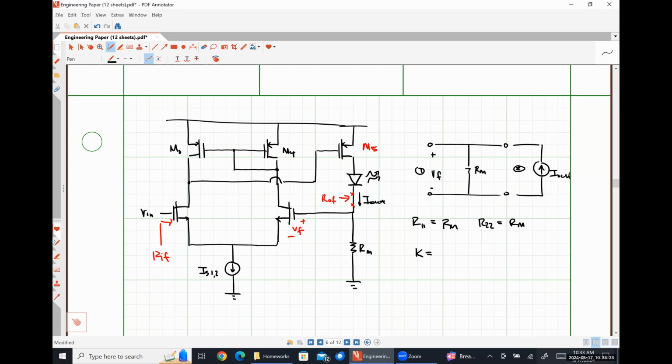It's literally that. If our input signal is a voltage and our output signal is a voltage, it's a feedback voltage amplifier. Input is current, output is current, feedback current. Input is current, output is voltage, feedback transresistance, whatever. So this one is definitely transconductance, on account of the input signal being a voltage and the output signal being a current. Feedback factor K.